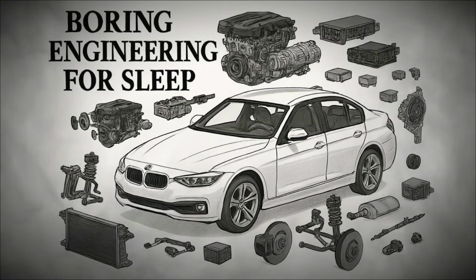Safety is also an integral part of steering design. The steering column is built to collapse in a collision, reducing the risk of injury to the driver. Modern systems are also integrated with electronic stability control, which can apply slight adjustments to help maintain direction during skids or emergency maneuvers. The overall purpose of the steering mechanism and power steering is to give the driver precise and effortless control over the car's path.